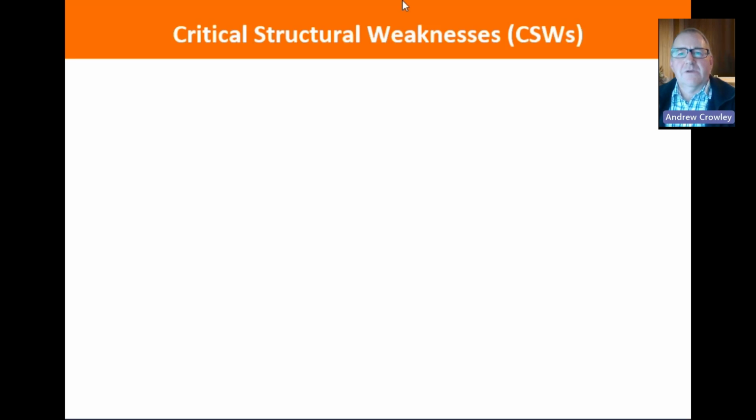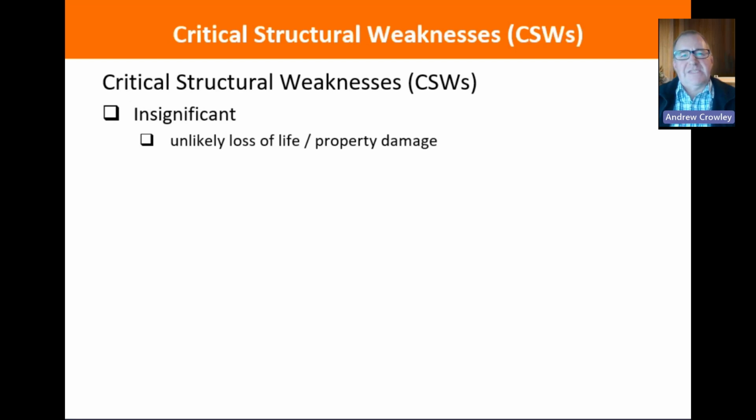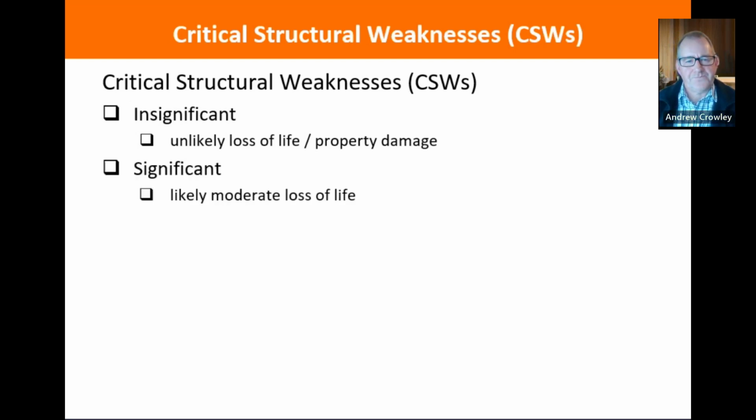What do we mean by critical structural weaknesses, CSW? So if it's insignificant, the real threat is unlikely to lead to loss of life or property damage. When we say property damage, we really mean next door, damage to neighbouring properties. If it's significant, there's likely to be moderate loss of life and likely to be damage to the adjacent property.